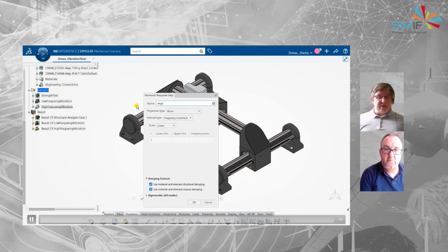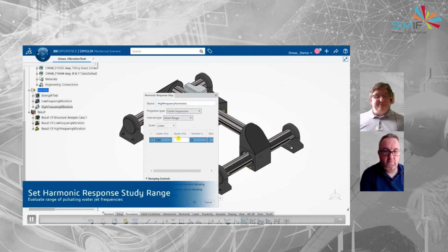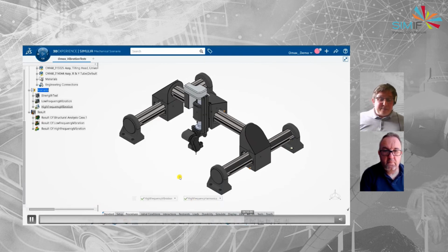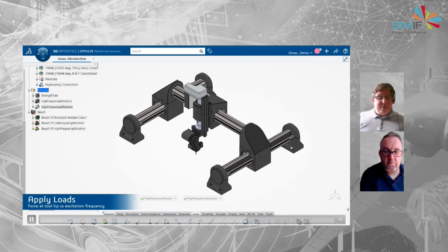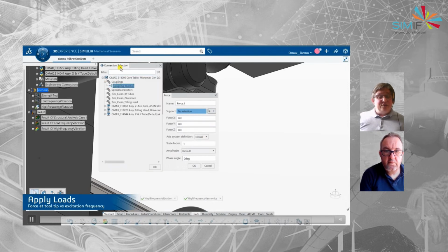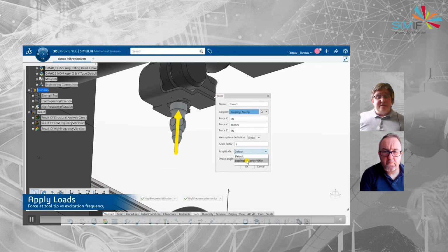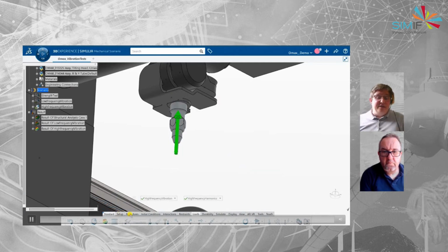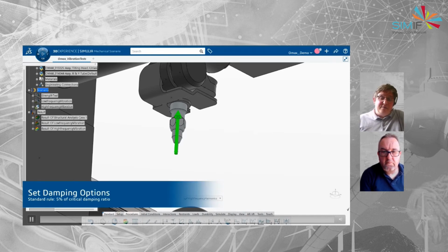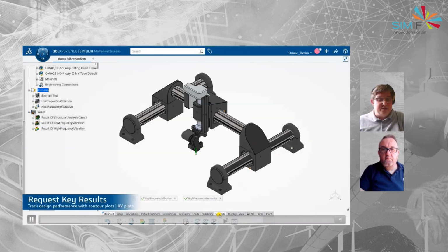So we're still setting up a whole host of simulations here. We've got the low frequency built now. We're just putting in the high frequency as well, and we put the loads in. So this is where we put the force of the nozzle forcing the water out, and like I said, about 88.9 newtons going up, so about 10 kilos. Putting in the frequency and how it all works, and adding the damping that we were discussing earlier.